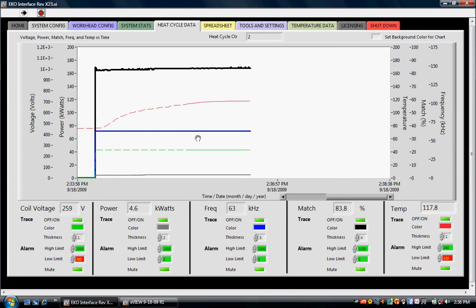eVIEW allows the operator to enter calibration information for this signal. Temperature monitoring is a key aspect of induction heating. Temperature measurements can be used to validate a new application or monitor an established process. An optional eVIEW accessory allows 4 external thermocouples to be connected to eVIEW.